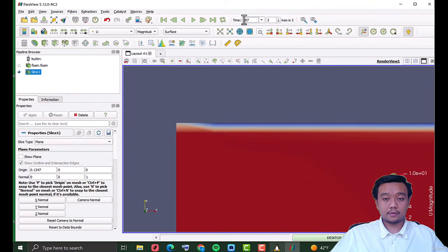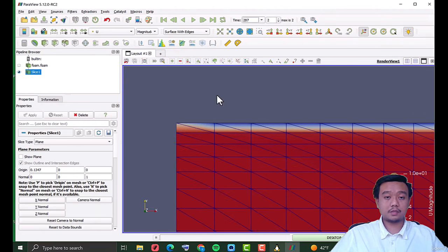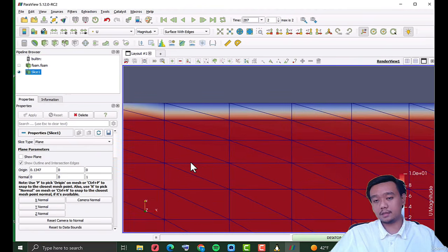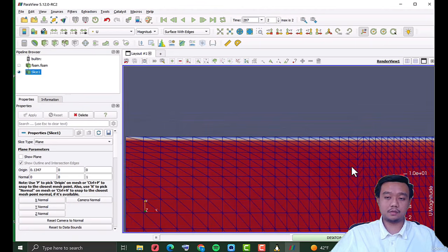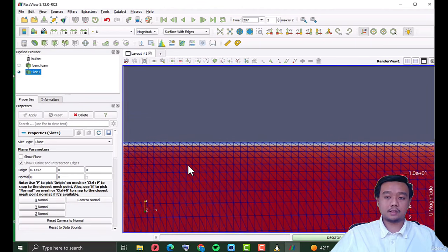And this is very crucial for the definition of the mesh, but we don't have quite a good mesh here to capture the boundary layer. But we don't have to worry much about this, because the wall function from the turbulence modeling covers this. But again, that is a tricky thing that we must discuss later in the turbulence modeling.